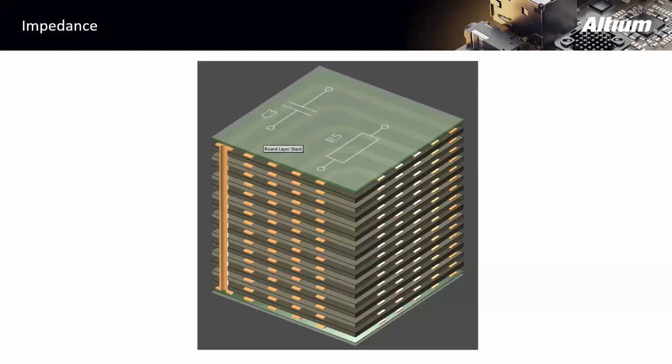If you take a look at the impedance, here we have the layer stack of our printed circuit boards. Like this PCB, we see that the layers are stacked upon each other. First, we have some overlay to protect the outer copper from corrosion, and perhaps also an overlay or silk screen with the component designators. Then we have the copper layers, separated by some dielectric. This dielectric can be of various thickness, basically making sure the copper does not make shortcuts from layer to layer. This is how the stackup is built, and this also matters when you are calculating the impedance.